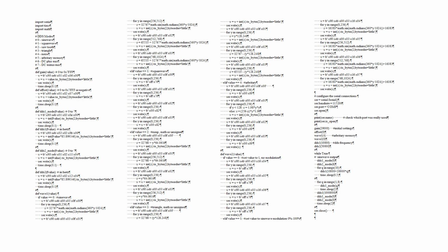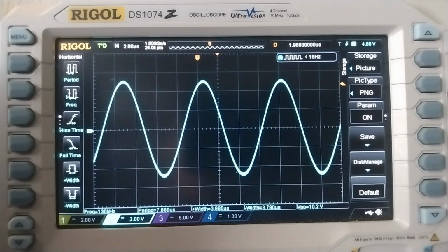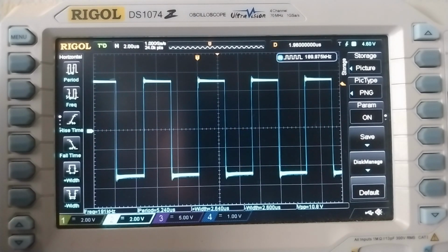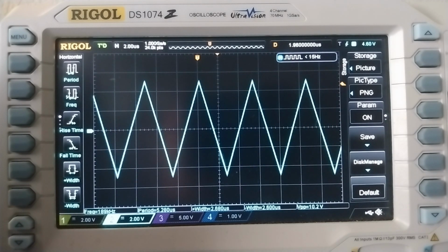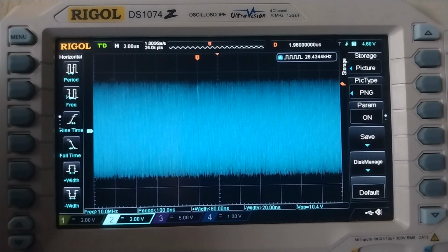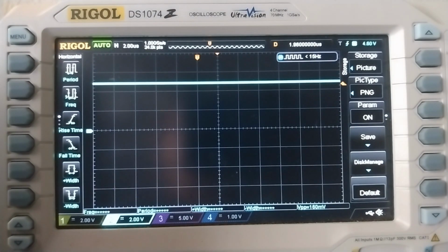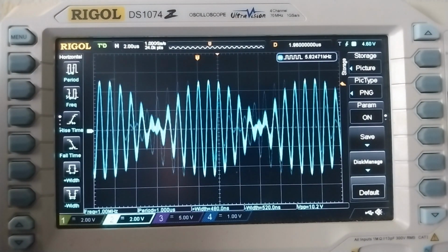Here's the Python code used to drive a demonstration video. The code drives the function generator outputs with increasing sine wave frequencies: square, ramp, triangle wave, direct digital synthesis from memory, noise, DC plus, DC minus, and then a sine wave modulated with a sine wave.